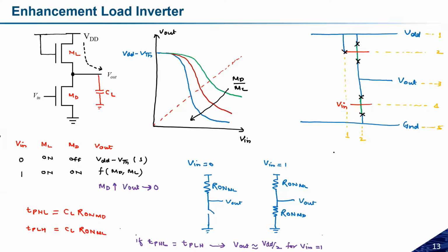If I want to calculate the W, it will be 5 layers plus 4 gaps, and by default we are considering the thickness of each gap and each layer to be 4 lambda. For someone it is 2 lambda, for someone it is 3 lambda, but for the worst case conditions I am considering it to be 4 lambda. So this W will come to around 36 lambda.